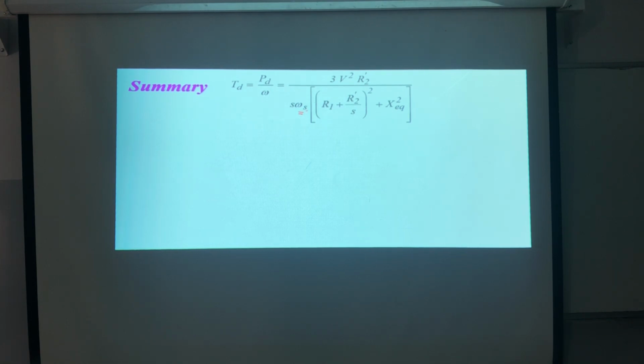If not, and I need to use the electrical speed, in this case, this is omega S mechanical. Do you remember the relation between the mechanical and the electrical? Omega mechanical equals 2 over P times omega electrical, so this will be P over 2, multiplied by TD. In this case, this omega will be electrical, and omega electrical, we know, is 2 pi F1.